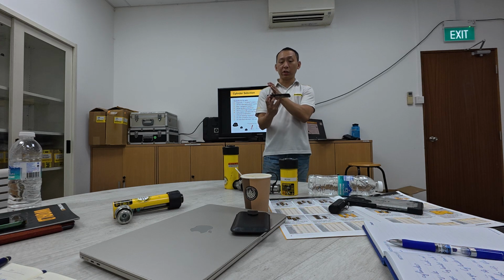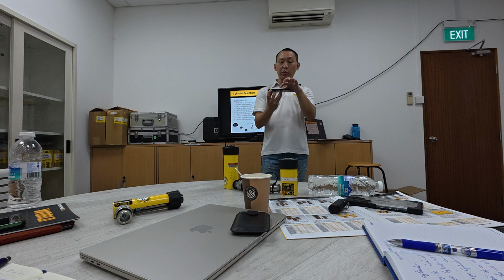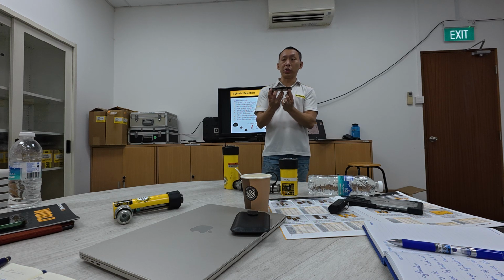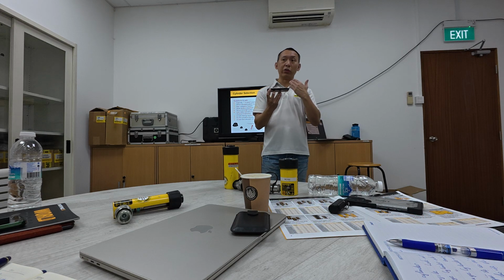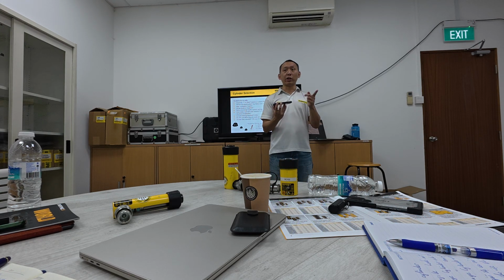Why? Because if let's say the majority of the load is here. In both sides, let's say this is 1,000 ton, I put 500, 500, 500. It's 50%. No matter what you do here, you still can take 1,000. You still can take the full load. So it really depends on how you're going to do the safety buffer, and this is up to the customer to tell you how much buffer they want. Not for you to tell them.